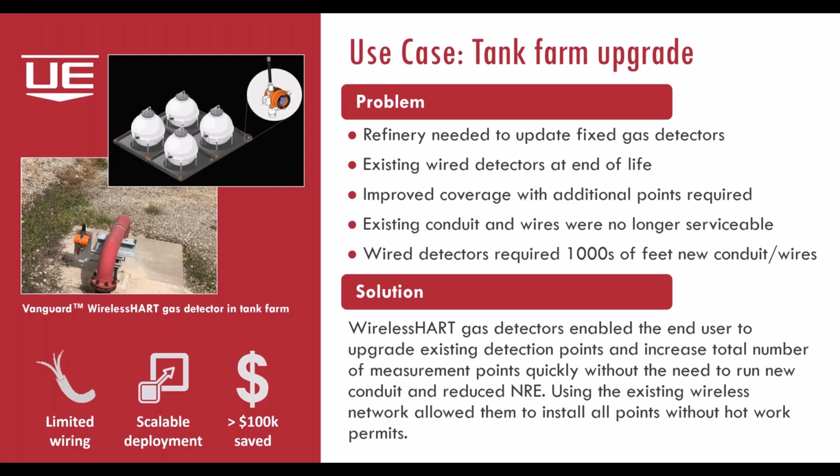They actually had a situation where when they initially put together the network, they were funneling all of the detectors through 2 detectors. They created a choke point, and the gateway was giving error messages about devices not connecting, and they would immediately know that they needed to go address something. And by having both manufacturers of the gateway and the device there, we were able to quickly determine that there was a choke point. And by putting in a couple more devices and repeaters, they're able to eliminate that, and the mesh became better. And now they're looking at 98, 99% uptime for the network without those errors.